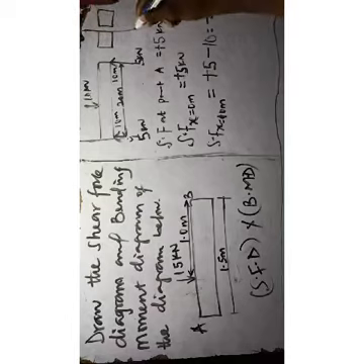So that is plus 5 minus 10. I want to take the shear force at x equals 10 meter. That means I'm cutting this at the middle. So I can have a diagram like this. If I cut this at the middle, that means we are not considering this part. We're only considering this part, and that will be the 5 minus 10 here. Because the 5 is acting up and the 10 is acting downward.